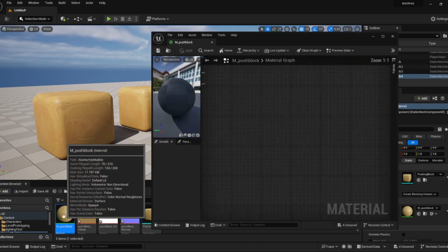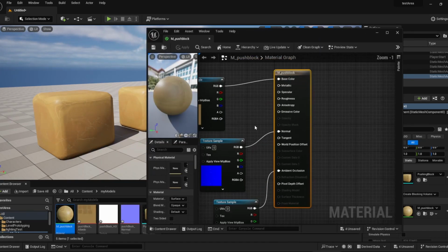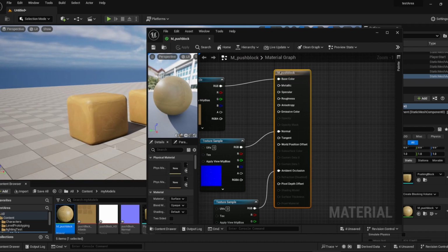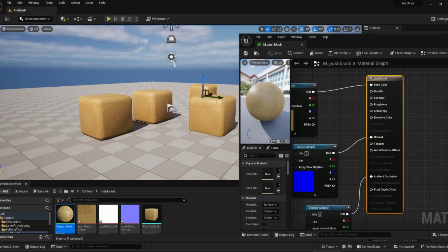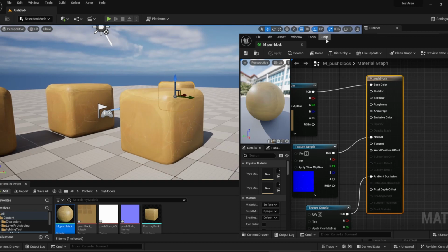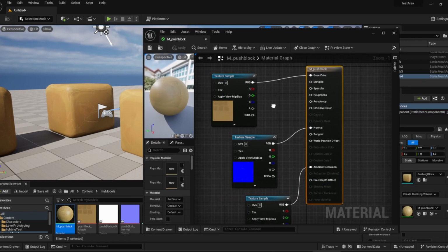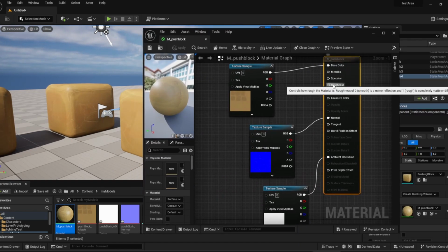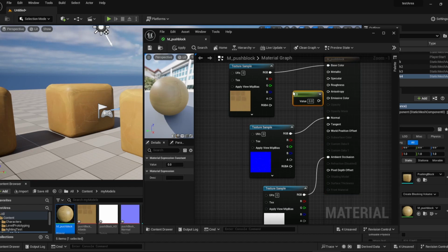Other things to think about here is it's quite shiny, and I don't want it to be shiny. I don't have a roughness map that I exported for this object, so what you'd want to do in that case, you can hopefully see that shine there, is switch off the shiny value. I'm just going to slot a node into the roughness slot. If I hold 1 on the keyboard and click, I can get a value here that I pop into the roughness slot.